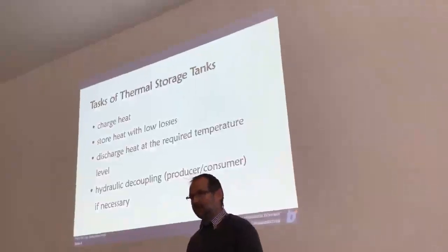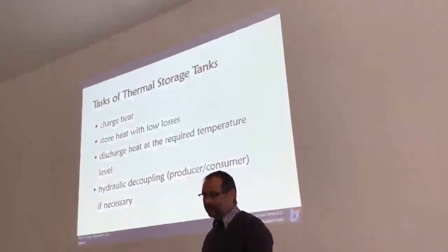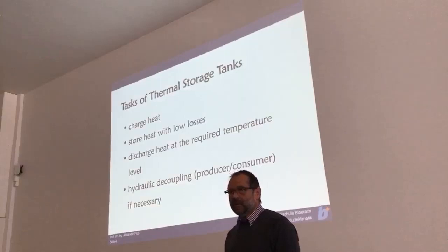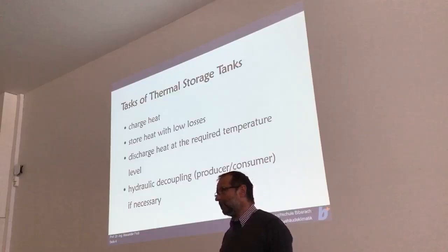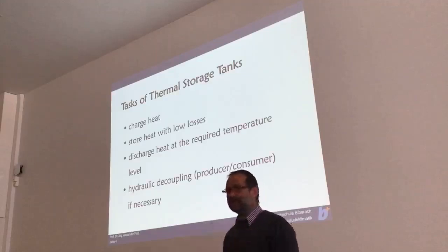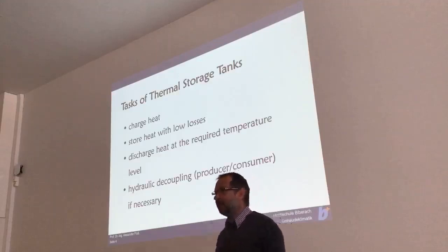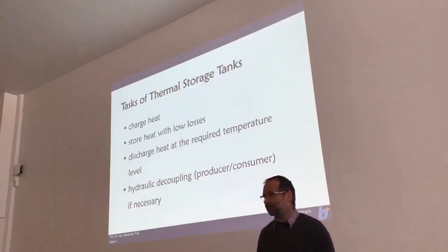Discharge the heat of the storage tank at a required temperature level. Imagine a storage tank which is cold, just 20 degrees of water temperature, and you fill that tank with water of a temperature level of 60 degrees, but you fill it just to the half, and then you get a mixing inside the tank. Then you have an average temperature of just 40 degrees.